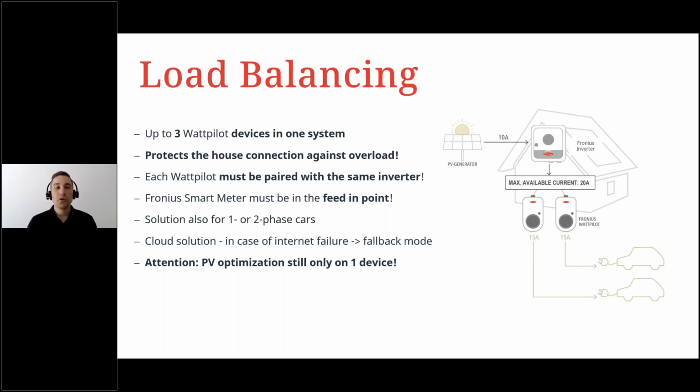Second, the Fronius smart meter in that system. Of course, the Fronius smart meter tracks the energy flows and therefore also watches the feeding point. And therefore, the Fronius smart meter must be at the feeding point. So please be very careful, all of you who are installing smart meters on a regular basis in the consumption path. Please make sure that it is not integrated in the load path, not in the consumption path, and therefore you need to install this Fronius smart meter at the feeding point.